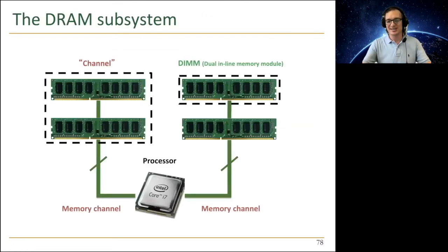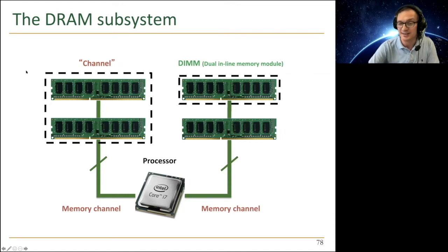Okay, so this may be a processor that you may have. Actually, for many systems, there's nothing special about Intel over here. All systems look kind of like this. They have multiple memory channels. In fact, more recent Intel processors may have 4 or more memory channels. You have memory channels so that you can access 2 different things at a time. That's one thing, concurrency. And you may also add more memory modules on each channel. That way, you get more capacity. So this looks like a real system with each channel having 2 modules. I just made it up. A module is also called a dual inline memory module in systems. You don't need to know exactly what that means.